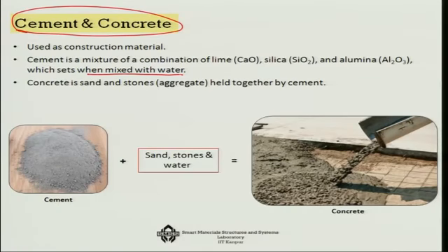In that sense the stones work, you can say, as particle reinforcement on a macro scale, a kind of similarity to composites. So they work like particle reinforcement, and the cement, the ceramic part of that, is like the matrix in the whole system. So cement and concrete is another very good example of ceramics.